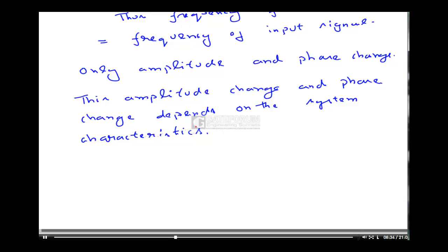So this is a frequency response which we are telling for any sinusoidal signal or exponential signal. Here we have taken the example of exponential signal. We can take an example for sinusoidal signal also. But e to the power j omega n can be written as cos omega n plus j sin omega n. So it is both cosine and sine added together as a complex exponential and we found the result. Okay. So these are the two things to be explained in linear time systems and signals.